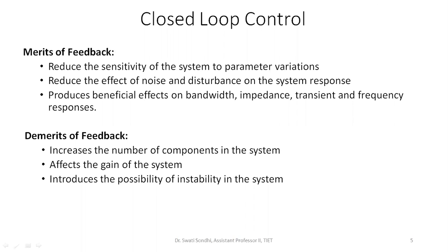That point is very important and very true: whenever we use certain elements in the feedback, mostly sensors, those sensors also produce some noise. The first thing is that the noise coming from the sensor is not of such a prominent magnitude that it can affect your system. And at the same time, we have certain filters. There is a controller, which is the whole powerful component that drives your system. And there is a filter, which we put in only to filter out the signal.